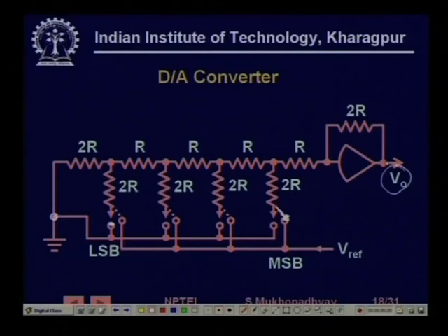That is very simple, because you have 2R and 2R in parallel now, since this is connected to ground. So, therefore, this resistance is R. Now, that R and this R are in series, so it is 2R, again 2R and 2R in parallel, again R and R in series, again 2R and so on. So finally, you get this network.